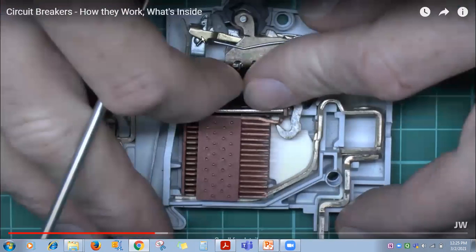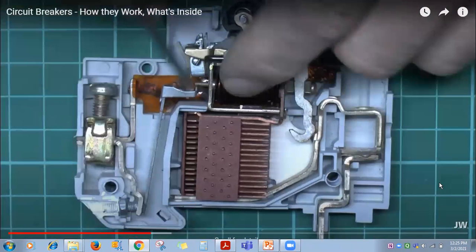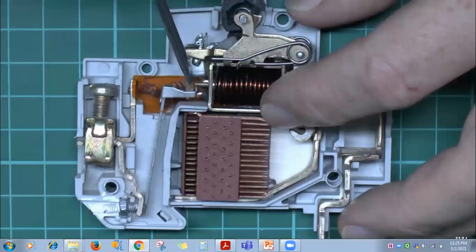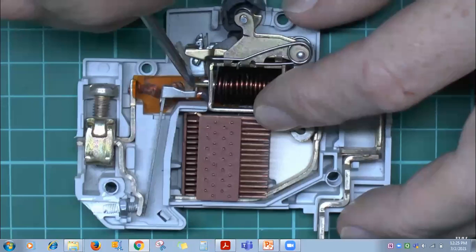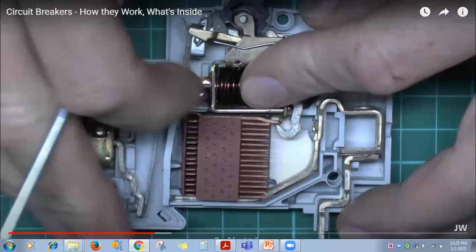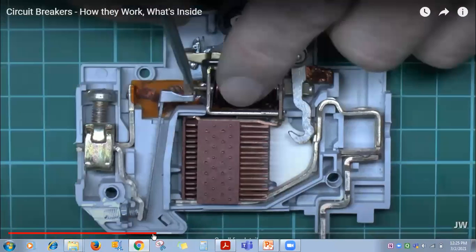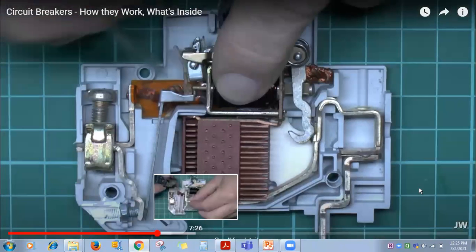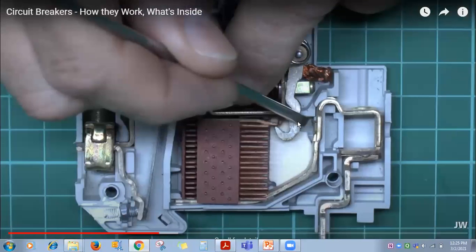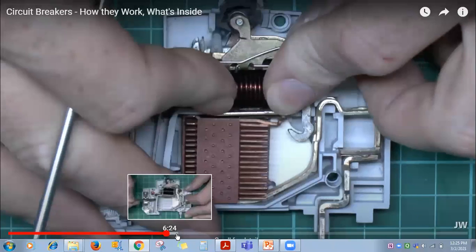This latch works and it trips off. See, again you watch. In case of short circuit, it occurs like this. See, there is a gap between the fixed and movable contact. Now it is the closed one. If you push it, through that latch these two contacts become open. Okay, so this is the short circuit.